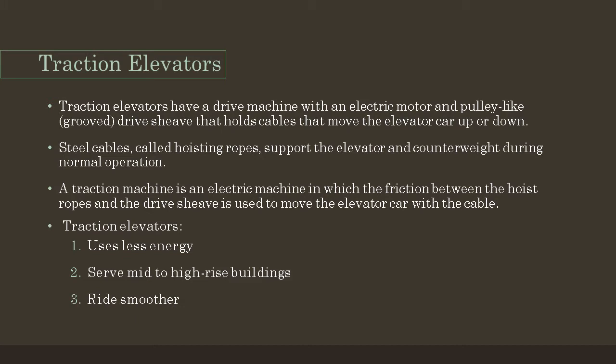Most traction elevators generally use wire ropes that are 1/4 to 1 1/4 inches, that's 6 to 32 millimeters, in diameter, and are composed of multi-strand soft steel wire wound around a hemp or polymeric core. Traditionally, the 8 by 19 wire rope, that's 8 strands with 19 wires per strand, pattern was used, but this is being replaced with modern patterns. Wire ropes must match the drive sheave perfectly to ensure that they have a long life.